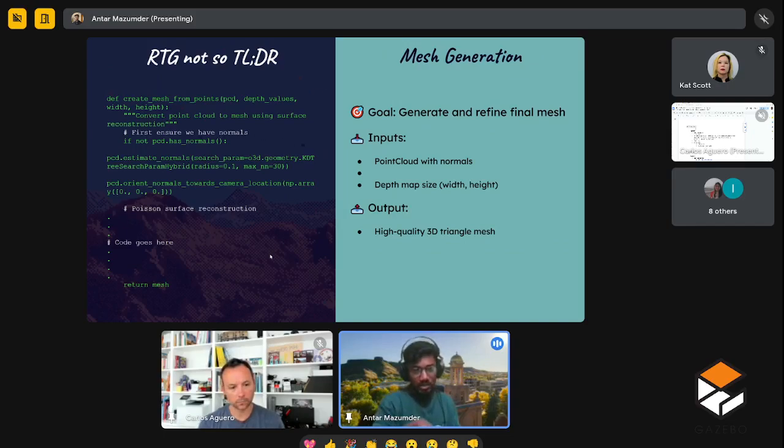So basically what it does is it wraps a sheet around the estimated normals. So you get a mesh, basically. It's a very high level overview, I know, but that's what it's doing. So then it returns the mesh, which is saved in your designated format. In my case, it was PLY and OBJ. OBJ can be directly exported into Isaac Sim, but for Gazebo, we have to do some post-processing.